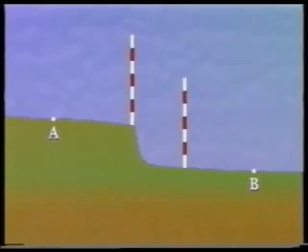Two ranging rods are located and the tape is held horizontally between them. Since this can be difficult to do very accurately, stepping should only be used for distances up to a maximum of 10 meters, and ideally a third person should be present to check that the tape is horizontal by viewing it from one side some distance away. If stepping is used, it must be remembered that the length obtained is a horizontal distance.